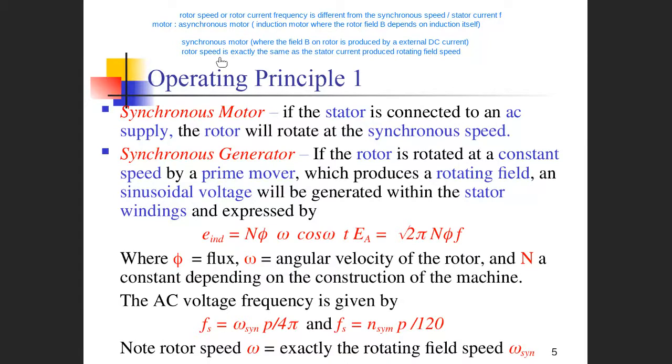But the synchronous motor, of course, has its pros and cons, advantages and disadvantages, right? That's why we do not use the synchronous motor as the power motors, which are induction motors. Because with the synchronous motor, you can imagine that even when it is rotating freely, you still have a big torque. That's dangerous. Okay, dangerous. So here that's why we're using the words synchronous and asynchronous.